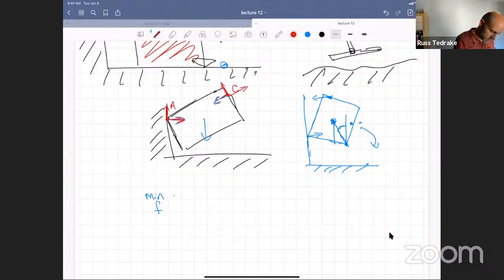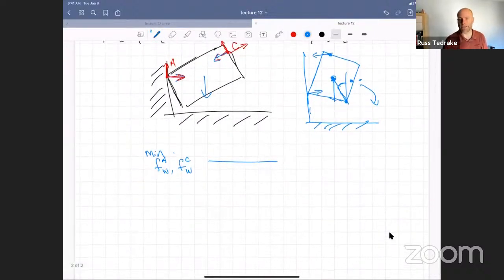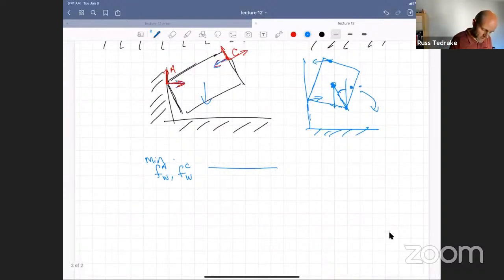I can use whichever decision variables I want, or whichever frame I want, but I'm going to go ahead and try to solve for both the force on the wall and the force at the box. I'll write it in world coordinates, but we're going to put constraints both on world and relative coordinates. Okay, I'll leave the objective for a moment. And of course, the first constraints are my friction cone constraints. So I'm going to say that